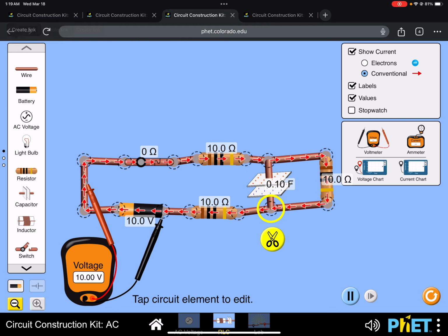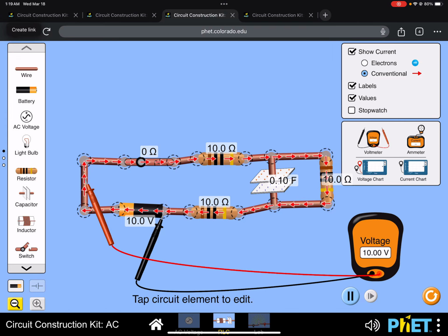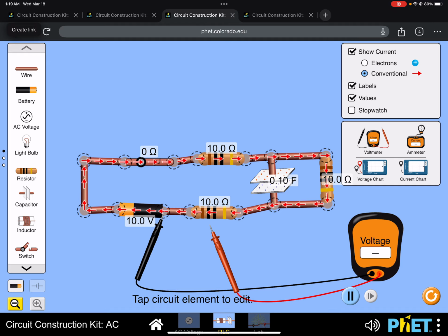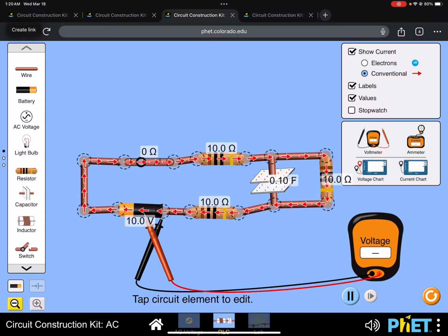Okay, so here the circuit has now reached a steady state, and we need to measure the voltage across the capacitor. So how do we know that it's epsilon over 3? Well, because we understand the principles of circuits. But in terms of actually solving for it, let's use real values. I know that the EMF of the battery is 10 volts, all right? And notice there's no current flowing through the capacitor, right?